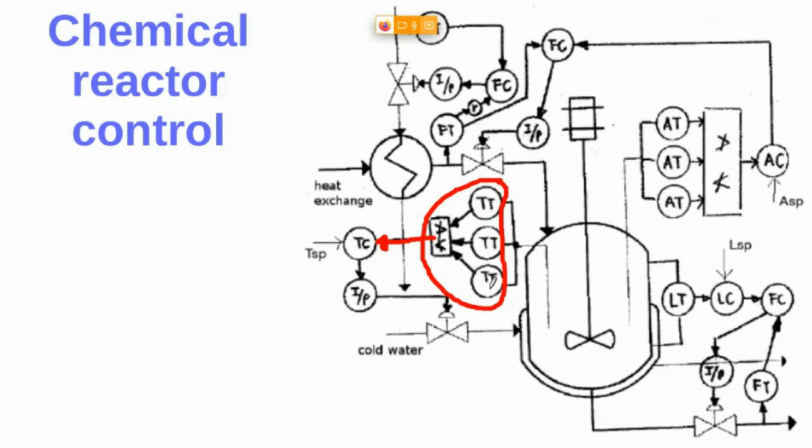So then you use 3 transmitters because 2 transmitters are giving you similar measurements, right? Not exactly the same, but so close measurements, right? And 1 transmitter is giving you, I don't know, it will depend on the fail, right? 0 or 100%, right? So because you don't know how it will fail, but you trust the measurements enough, just because you only consider that one out of them can fail at a time, right?